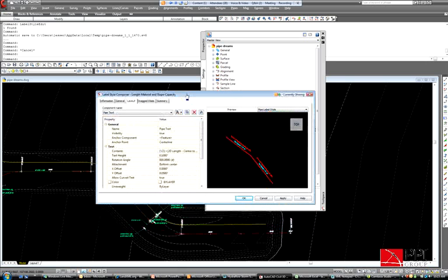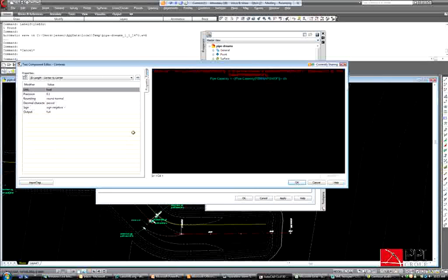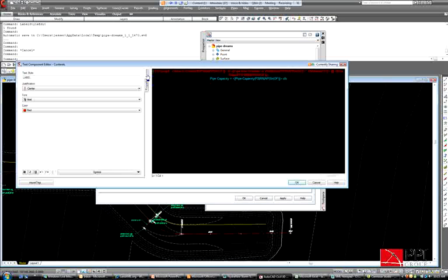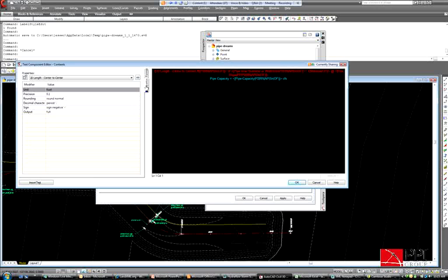And so breaking open this label style, for those of you that have been using this for a bit, you come in, edit the label style, come to the layout tab of that label style, and the contents is where the meat of the label style is. You can just click on those ellipses and start to affect everything from the formatting of how that label style shows up to also the properties.